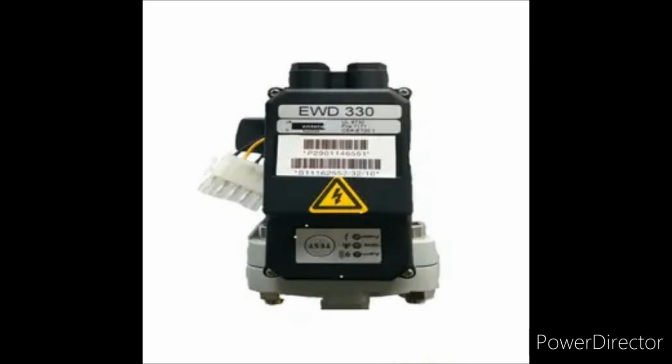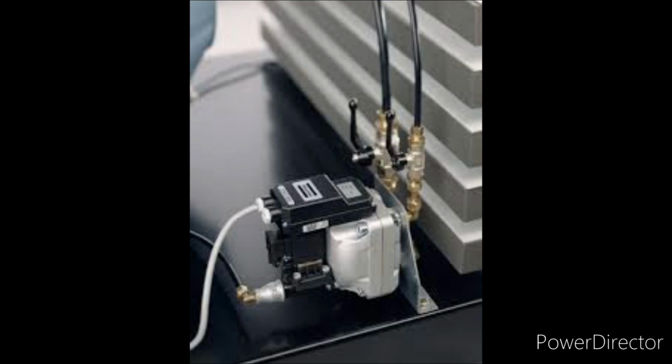And auto drain valve. So what to consider during its purchase? That is also important. There are various things you should consider when buying an air compressor automatic drain valve. Firstly, it is important that you choose the right thread so that your drain valve easily connects with your air compressor. Look for a male NPT inlet as it goes well with most air compressors. If needed, you can use a reducer so that it works properly.